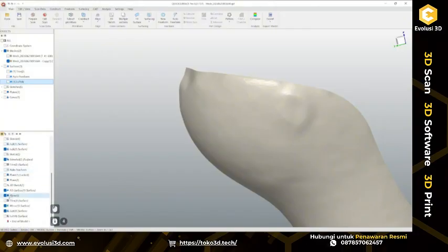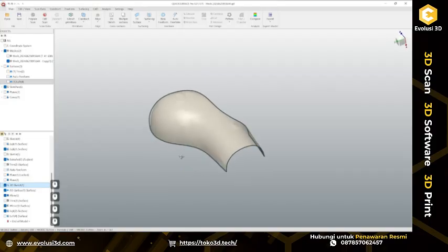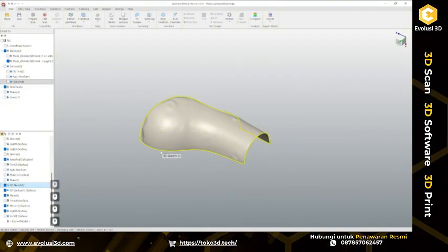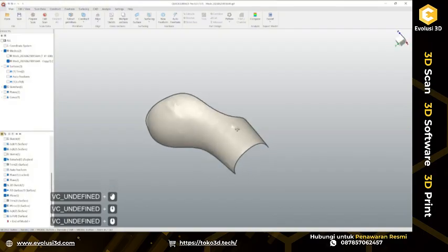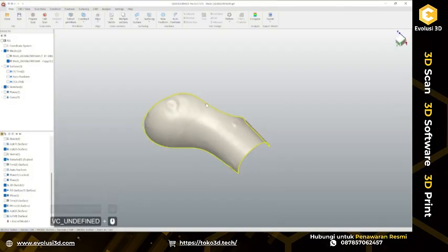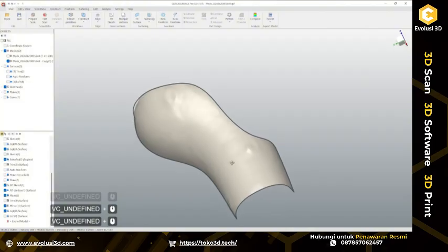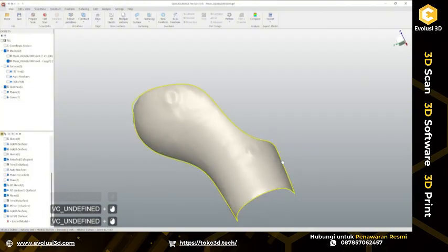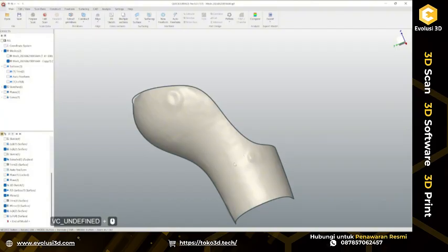And now let's move to actual lofting and a small discussion about loft, and in general maybe about multiple sections and lofting them into one surface. From lofting we expect to have a really nice result if we try to use all these curves to loft them. But in fact loft is quite a complicated tool, and typically it takes the length of this curve, matches it to the length of the next curve, and then tries to form a surface in between them.